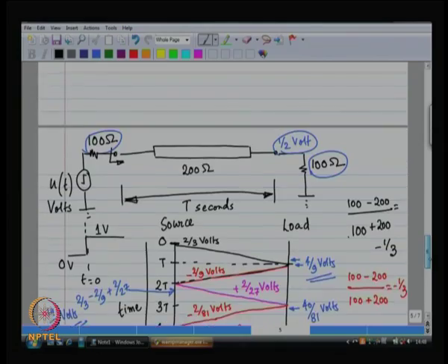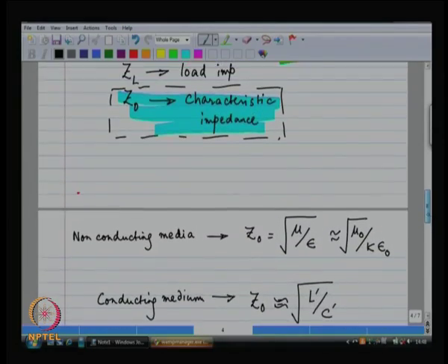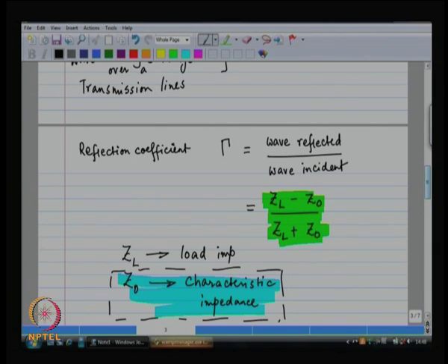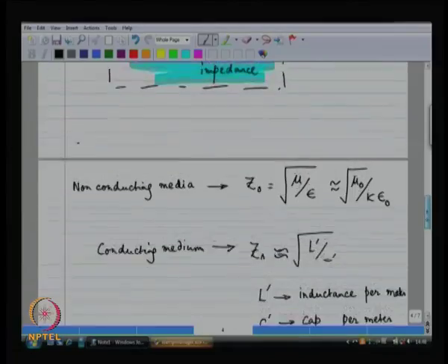If you know how many dB of loss you are having per kilometer, then it is just a simple addition on top of this, right. The other thing that changes when you incorporate loss is that this parameter Z naught no longer remains a real number, it could very easily be a complex number. Z L, Z S, these could also be complex numbers, in which case gamma itself is a complex number.